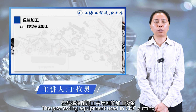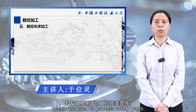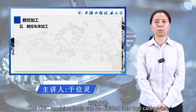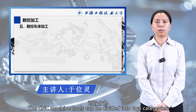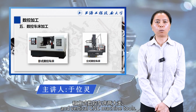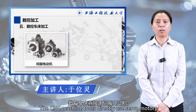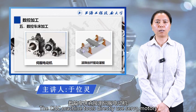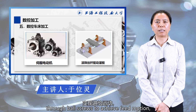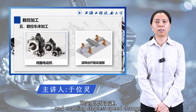The processing equipment used in CNC cutting is CNC machine tools, which are used to process rotary parts. According to the structural form, CNC machine tools can be divided into two categories: horizontal CNC machine tools and vertical CNC machine tools. Compared with ordinary machine tools, CNC machine tools directly use servo motors to drive the slide and the tool holder through ball screws to achieve feed motion, thus greatly simplifying the feed system and enabling